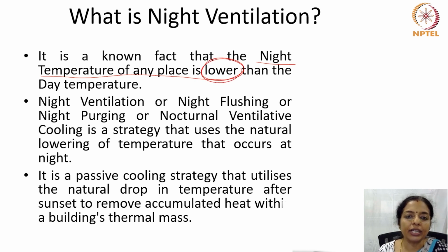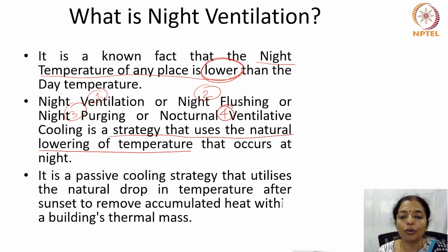Night ventilation or night flushing or night purging or nocturnal ventilative cooling, these are all the same things, and it is a strategy that uses the natural lowering of temperature that occurs at night. It is a passive cooling strategy that utilizes the natural drop in temperature after sunset to remove the accumulated heat within a building's thermal mass.